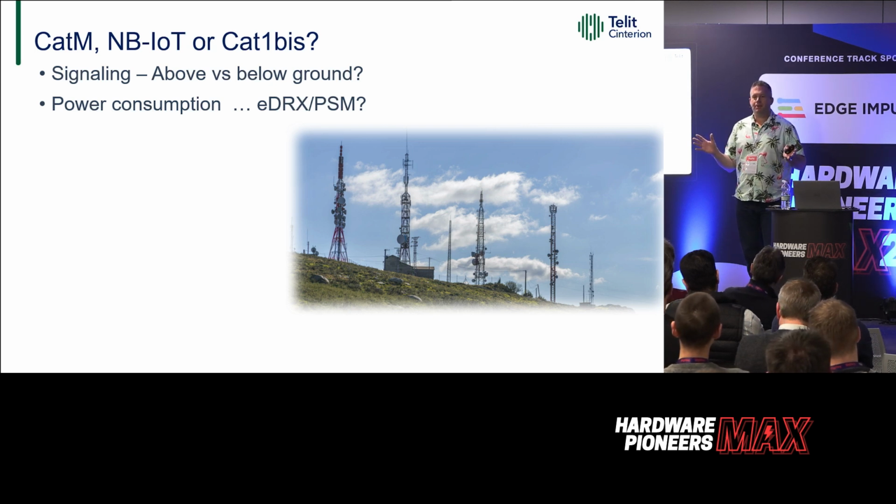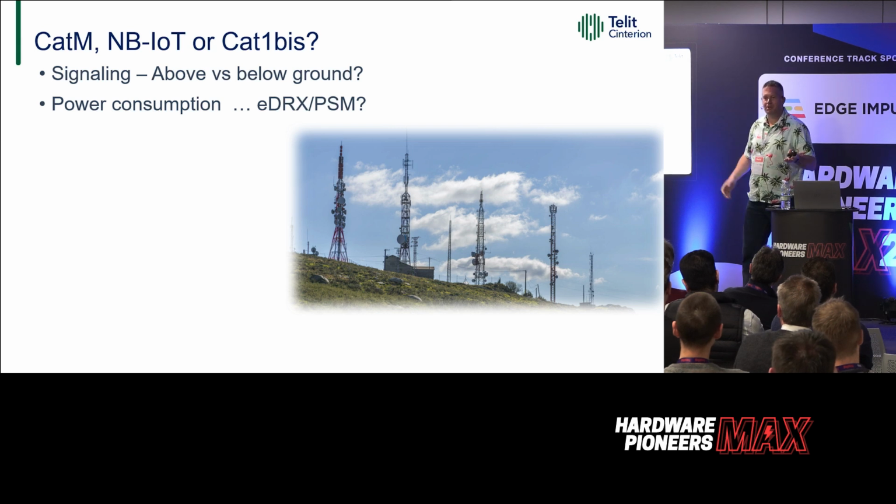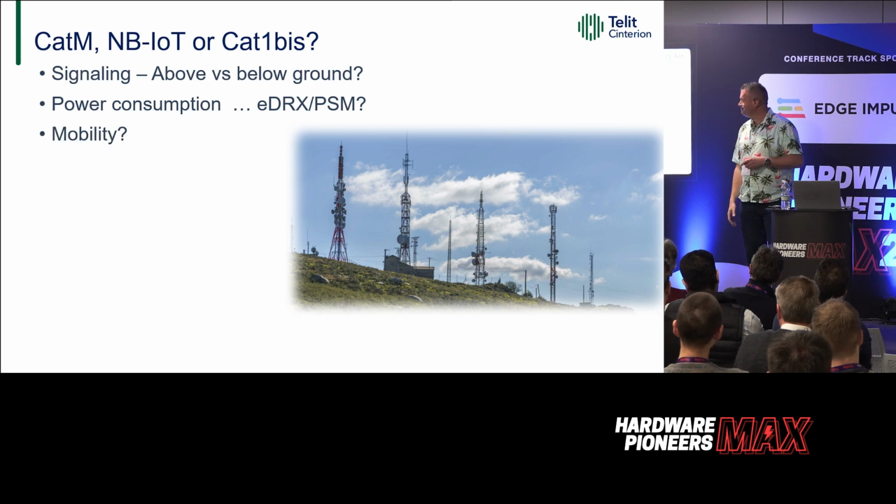And then you talk about, well, how are you actually using the modem? Are you doing what you've done for 25 years and turning it on, letting it register, transmitting a few bytes of data, checking the server for return packet, and switching it off again? Yeah. Okay, we don't need EDRX and PowerSave mode then, because you're just turning the modem off. And maybe you're doing that once a day, maybe twice a day. But in those circumstances, it doesn't make sense to even worry about that sort of technology, right? It's all about how you're using the tech.